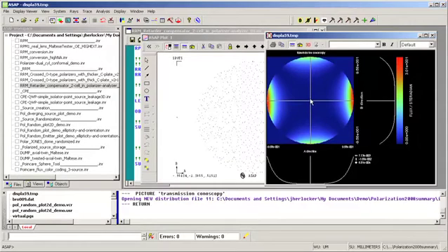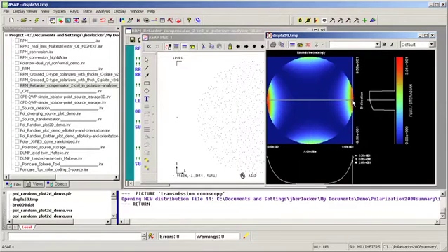So this is the transmittance as a function of direction for a simulated liquid crystal cell. It is dark in the middle because it is an off state. We want to have the transmission as low as possible. So in the center, its performance is very good. Along the diagonals, its performance is very good. But along the x-axis direction, there are a couple of bright spots near the edges of the visual field. And a good compensator design seeks to minimize that, and in fact can reduce it by orders of magnitude.